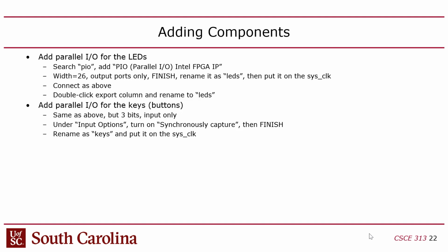I just bought a new car, and when you open the door all the lights are LEDs, and they brighten up and then dim down, right? All LEDs use this brightening and dimming effect now. You see it everywhere, but it's handled through pulse width modulation, and that can be controlled with software, but it's usually controlled by hardware because controlling PWM is kind of too basic a task for software to be doing, right?